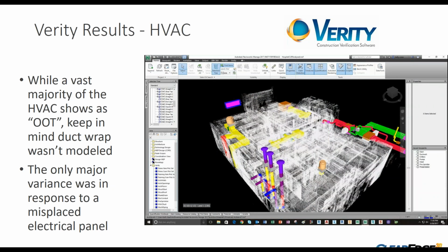And it's worth making a point here that one of the fundamental premises of the software is that what you have modeled closely corresponds to what gets scanned in the field. And so Tim alluded to this a little bit. The duct was a pretty challenging thing on this job to analyze because the sheet metal was modeled, but this was all wrapped duct. So what was installed in the field was roughly 4 inches bigger in every direction with traditional duct wrap that was shiny and it sagged on the bottom.